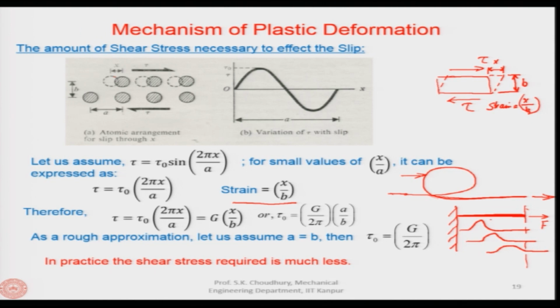So, this is an analogy. It is kind of a defect in the lattice structure, and all these defects are made so that the shear stress or the force required for creating the deformation, or the slip, could be much less, all right.